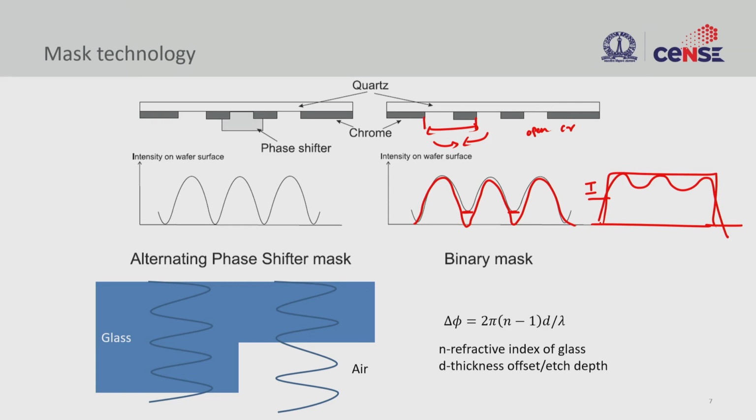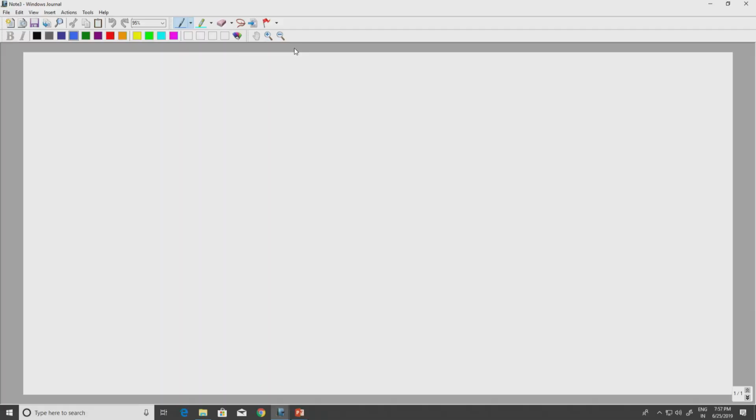In this case, what we do is we use a phase shift mask. So let's look at how this phase shift works. If I have the opening, something like this, let's look at the electric field. The electric field can be positive and negative. So the field is like this, let's say in this case, and then also positive in this.